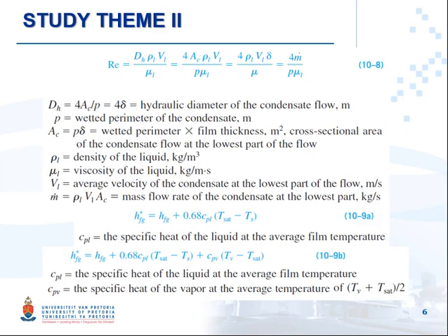For the flow regimes, wavy-free, wavy laminar, or turbulent, the way that we find the Reynolds number is the same. In film condensation, we just need to keep in mind that the hydraulic diameter is, as you can see here, delta. What is delta here is basically the film thickness.